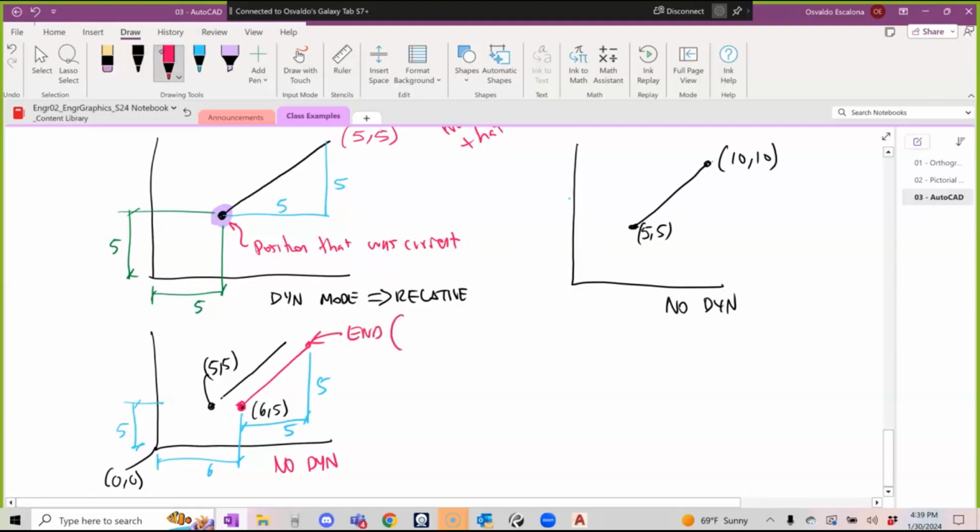The coordinate will be how much I'm moving in X, and how much I'm moving in Y. So I move 6 and 5, it's 11, and in Y it is 5 and 5, which is 10. So I hope that you guys see that now I'm doing absolute moves. I'm giving it a coordinate based on the absolute 0,0. Does that make sense? Bueno.